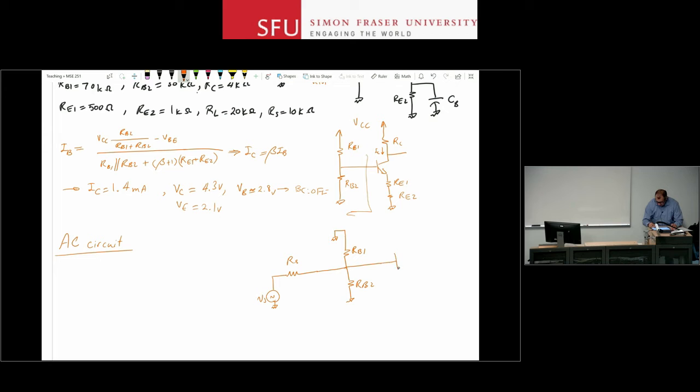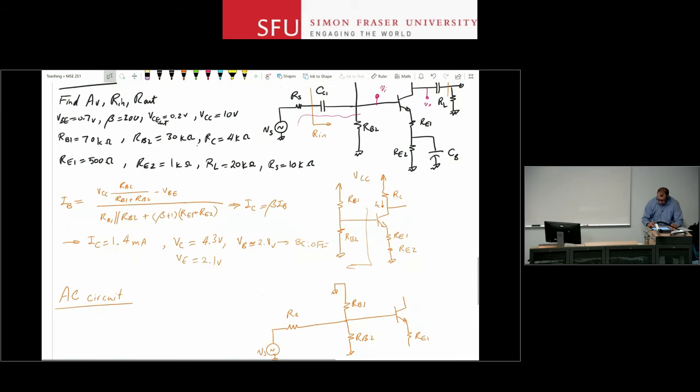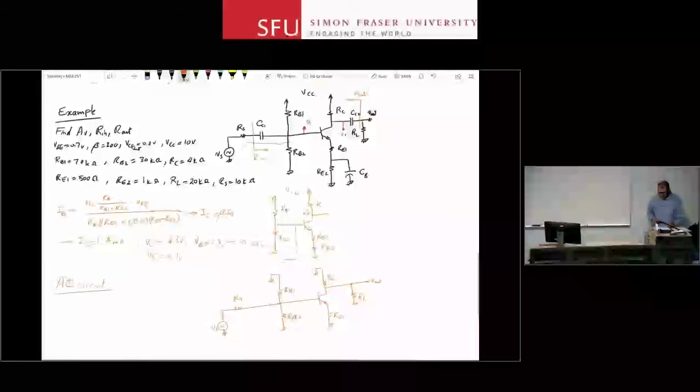Then I have my transistor here, RE1 in the emitter circuit, and then RE2 is now bypassed by the capacitor, so it's replaced with a short circuit to ground. RC here goes to ground again at the top. The coupling capacitor at the output is now shorted as well. This is Vout, and RL is here. Right? So I call this the AC circuit.